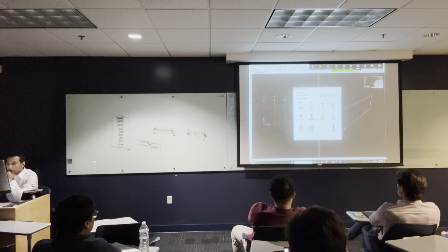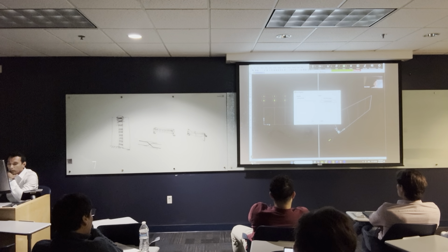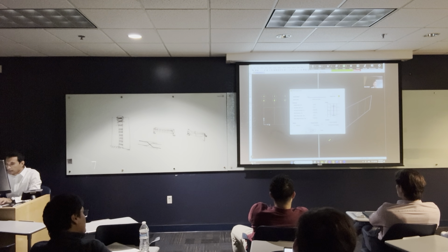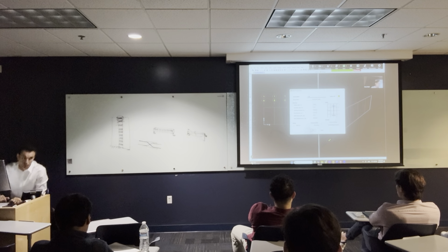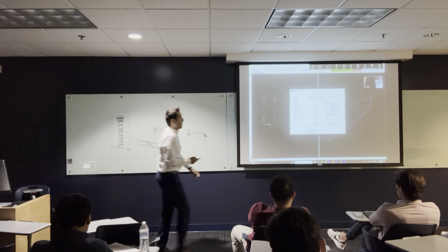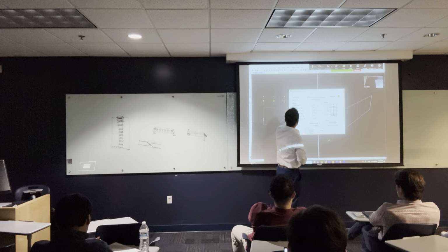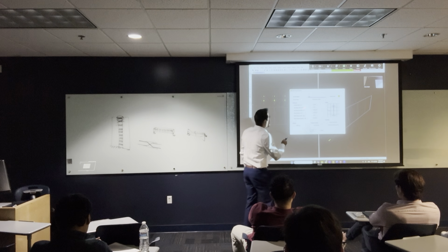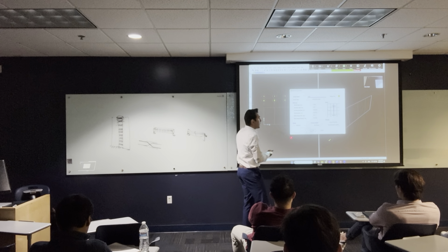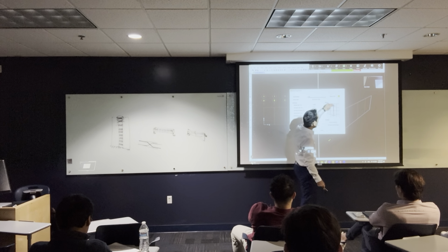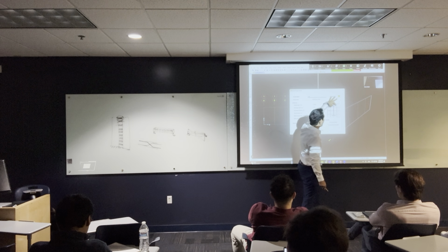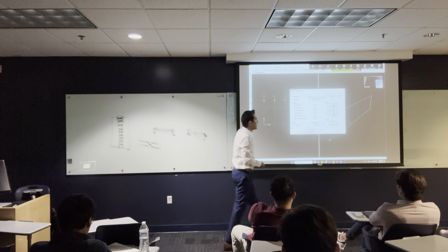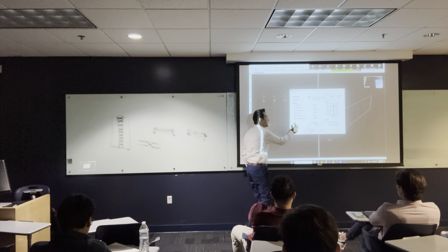So if I want to define a steel section, you can click, let's say, on the I-beam, and in the I-beam you have to define, let's say, I-500 or something. You have to define all the information about the I-beam. You have to define the outside height, the top flange width, the top flange thickness, the web thickness, the bottom flange width. You have to define the parameter of each one. This flange, width and thickness. This width and thickness. The bottom flange, width and thickness. You have to define all these. And you have to pick the material.